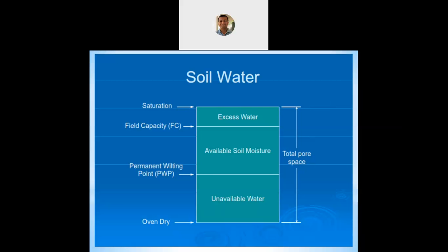So after some time a status is achieved which is known as permanent wilting point. This permanent wilting point is also known as the lowermost limit of plant available water. What happens here is that beyond this point, if we do not apply irrigation, then the plants will ultimately die. So basically the water present between field capacity and permanent wilting point is available to the plants.